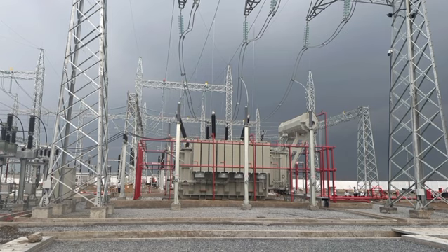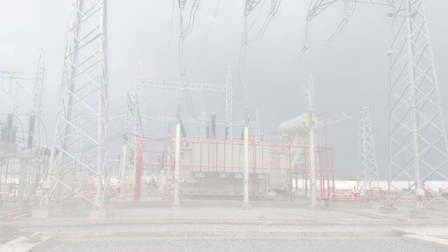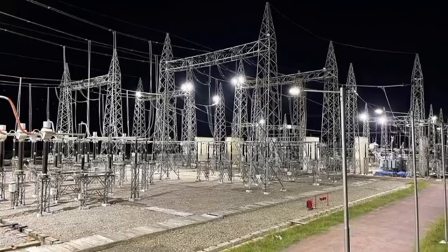Design considerations. When designing a 220 kV substation, engineers consider forecasted load demand and fault levels, geographic and environmental conditions, land availability, AIS versus GIS, future expansion possibilities, safety and accessibility, and cyber security in SCADA-connected substations.